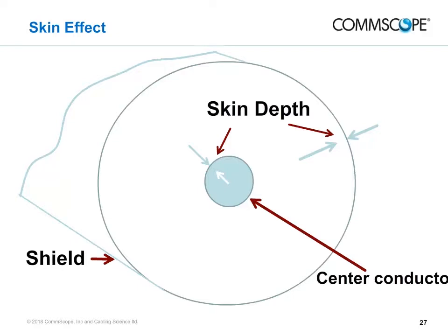Skin depth has several implications to cable manufacture and handling. For example, proper tools need to be used to prepare cable for connectorization, since it only takes a nick in the center conductor or shield to very markedly decrease current flow. From a manufacturing standpoint, a cable made with copper cladding over a less expensive core can have the same electrical properties as a solid copper conductor.